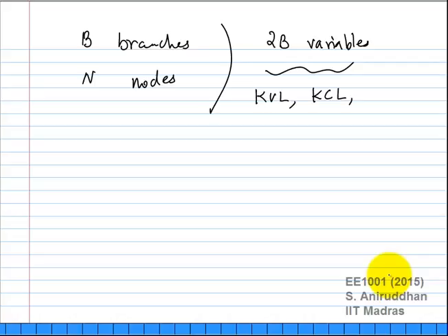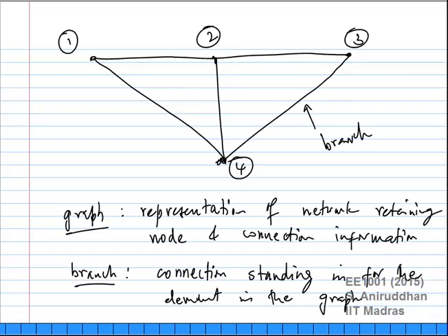We are going to see that it's n minus 1. N equations can be written, but only n minus 1 independent equations, and let us see why that is. For each one of these I can write, let us assume the reference that the sum of all currents leaving the node is 0. I can write the same thing here. I can write the same thing here.